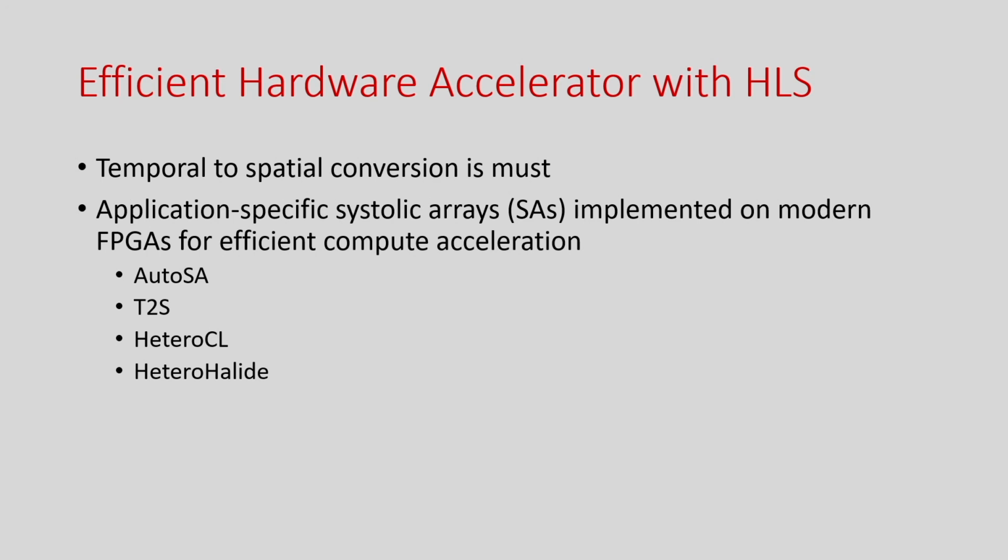And as we understood in the class with the matrix multiplication example, once a big computation is happening, if you just do it sequentially, you are not getting the power of the hardware. Specifically in the FPGA, there are a lot of CLBs running in parallel, a lot of DSPs running in parallel, a lot of RAMs running in parallel. So, unless you parallelize your input C behavior, you will not get the performance.